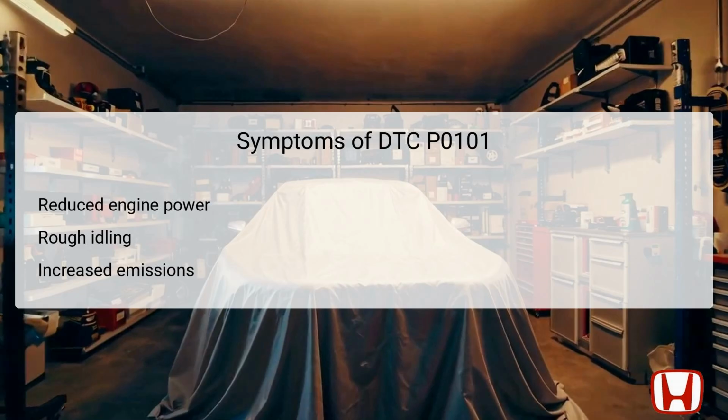When DTC P0101 is present, various symptoms may manifest, affecting both engine performance and vehicle behavior. Reduced engine power is one of the most noticeable symptoms, with drivers experiencing sluggish acceleration and an overall lack of responsiveness when pressing the gas pedal.